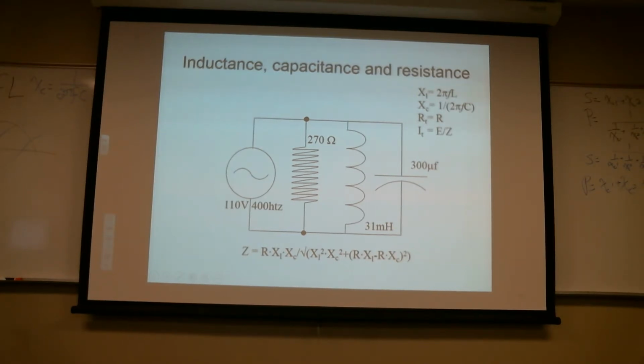Anytime you have current going through two conductors that are fairly close to each other, or very high voltage, there's a capacitive relationship between them too, right? So it always exists. That said, anytime you run a lot of current through a wire, you're going to get the wire hot, which means resistance, and you're going to create a lot of magnetism, which means inductance.